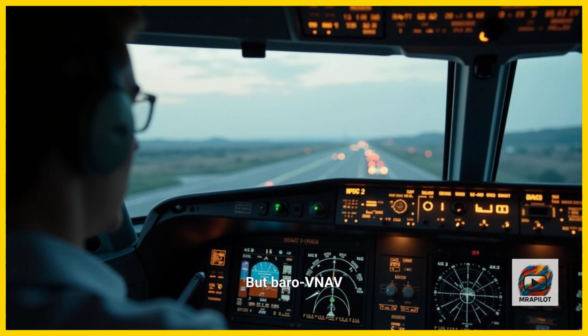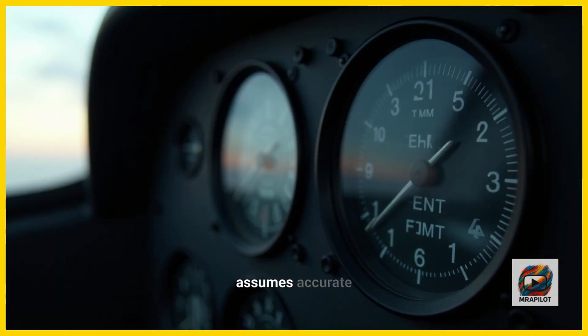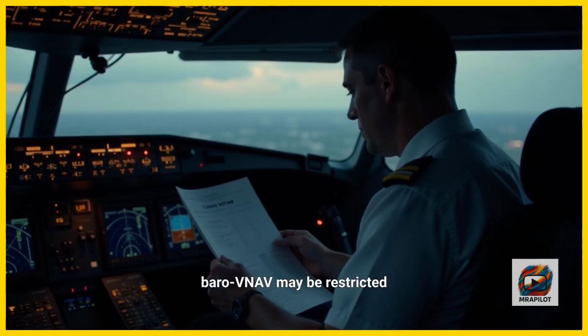But BaroVNAV has limitations. It assumes accurate temperature and pressure. If conditions deviate too far from standard, approach minimums increase or BaroVNAV may be restricted altogether. Always check NOTAMs and temperature limits in cold weather.